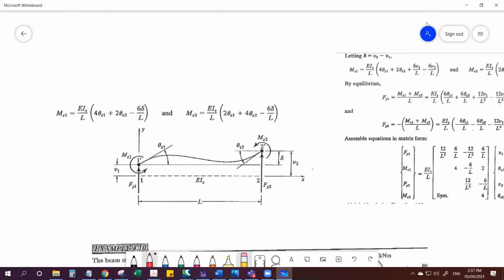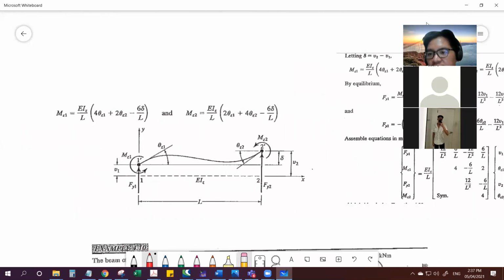And if you notice, even if you model in STAAD and analyze your building, the beam will most of the time have no axial force, no? Because the beam will behave in bending. That means it's justified to assume there's no axial deformation, therefore no axial force.